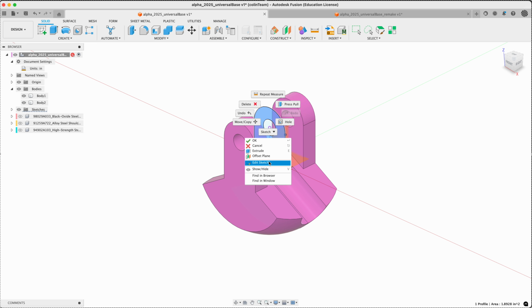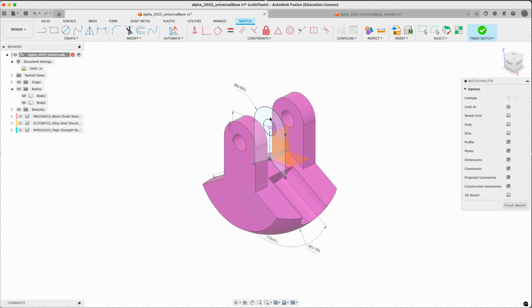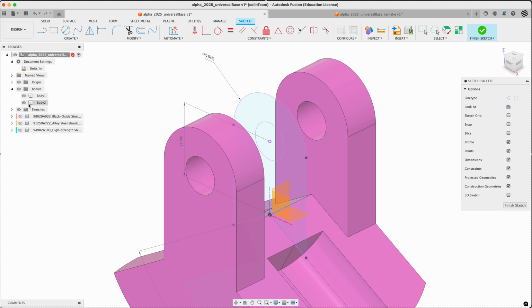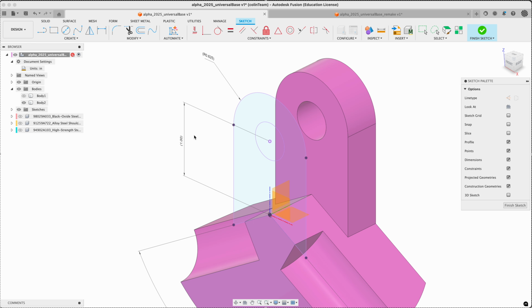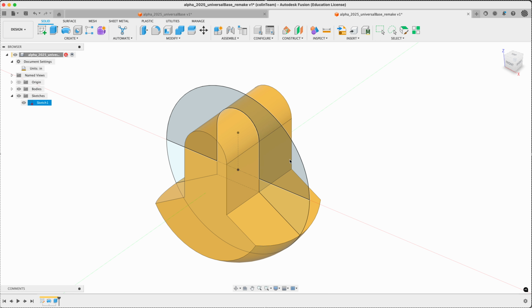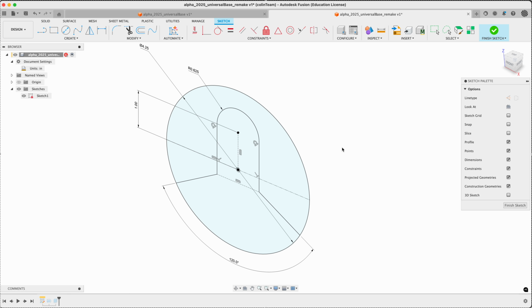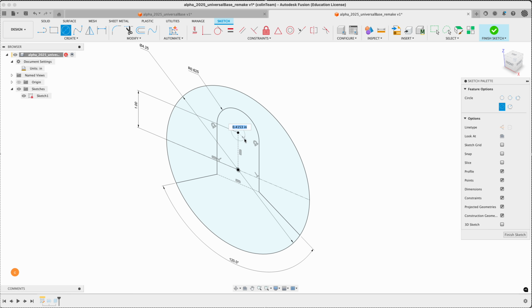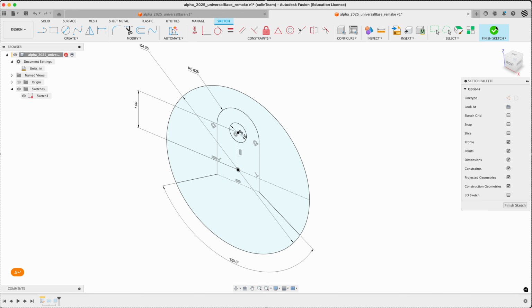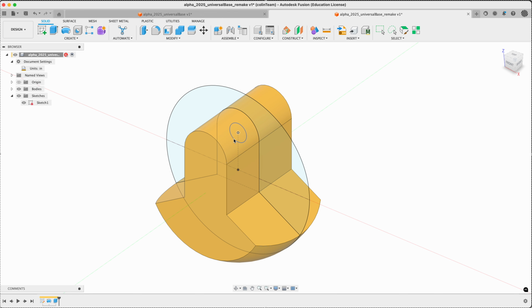It's running. Edit sketch. We can hide the body we don't like. Wrong one. Dimension. Be careful here, that's a diameter, 1/2 inch. Edit our sketch. Circle C. Just type in 0.5, enter. Finish the sketch. Notice it doesn't pick up.